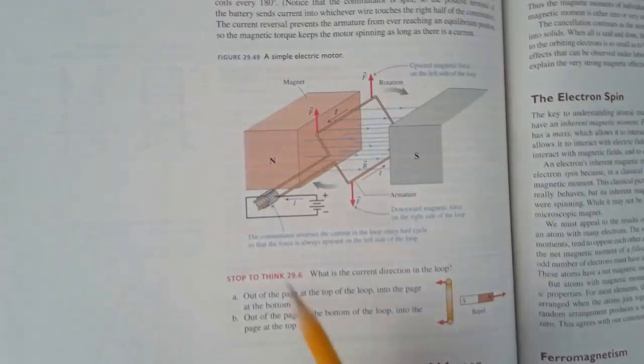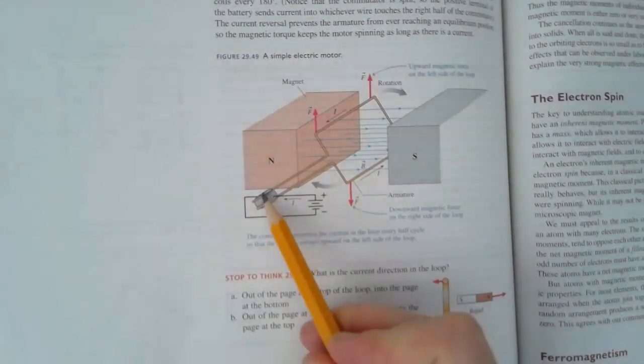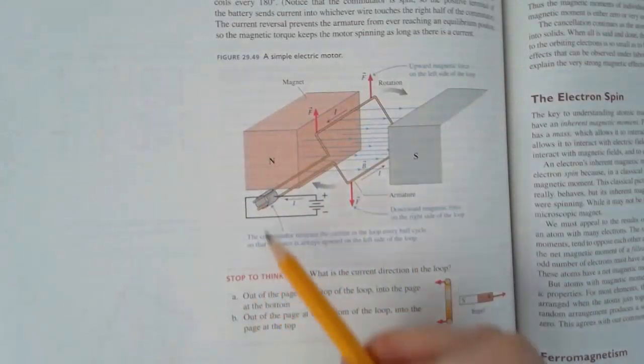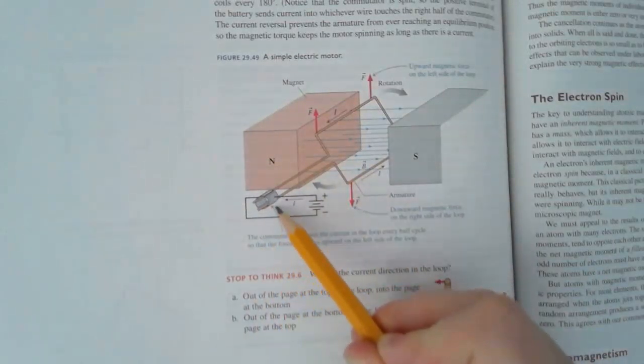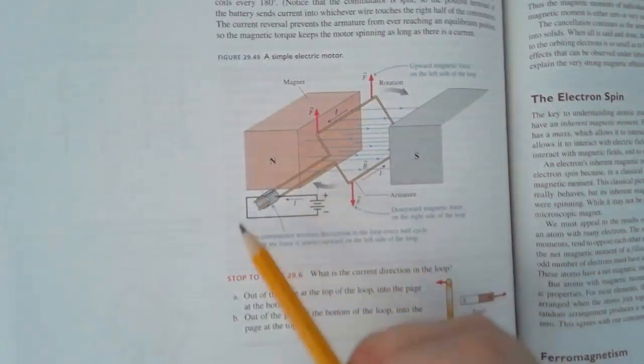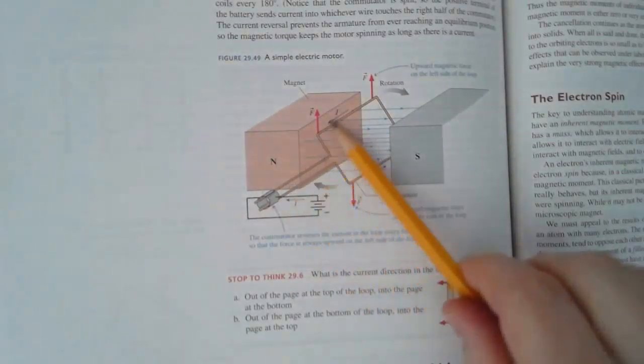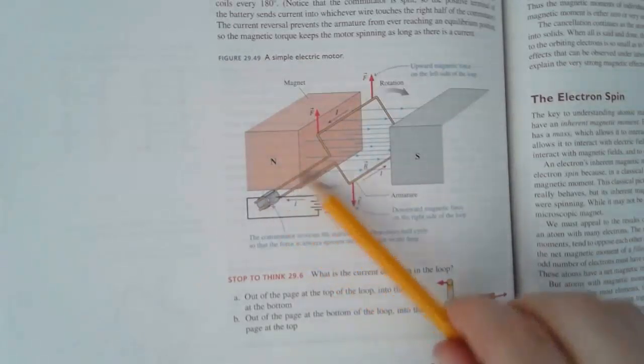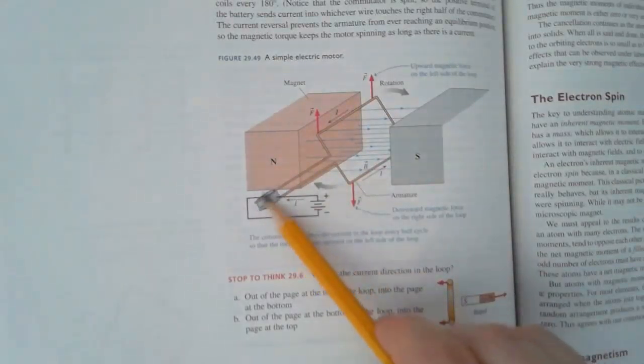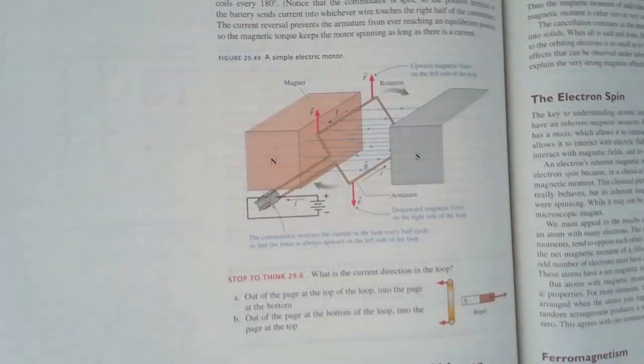Now the real electric motor might have more than just two connectors to make the whole thing smoother. It might be split into 4 or 6 or 12, with alternating plus, minus, plus, minus. But that's beside the point. The basic principle is this reversing direction of the current using this commutator method.